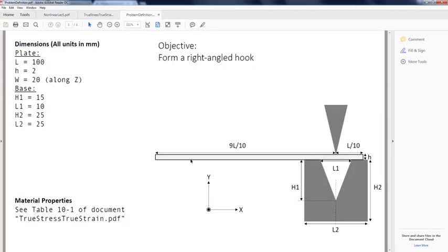So this entire part is actually just for showing. We can model this problem as a symmetric problem with a symmetric boundary condition on the left edge, and we only model the right part of it. So we are going to do this.